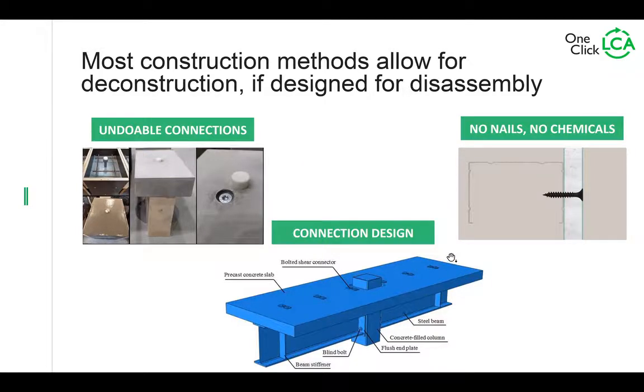And if you have connections that you need to embed, don't embed them in cement-based concrete. You can embed them in gypsum-based concrete, for example, so it's easier to open. And avoid chemical-based bonding, and do avoid nails if you can. So materials just can be simpler and unfastened.